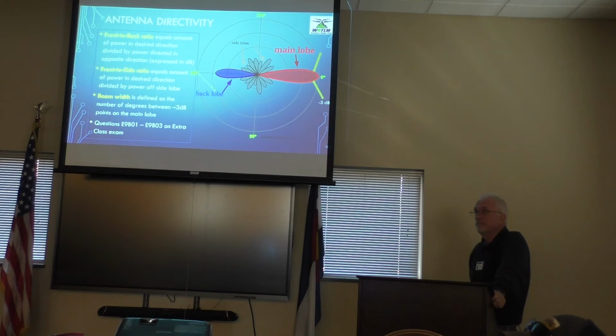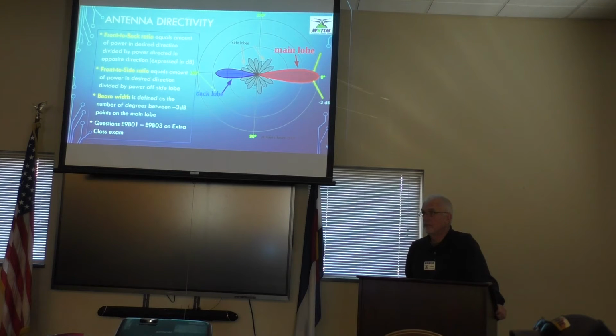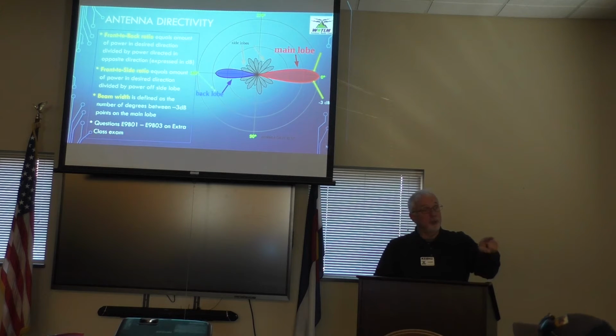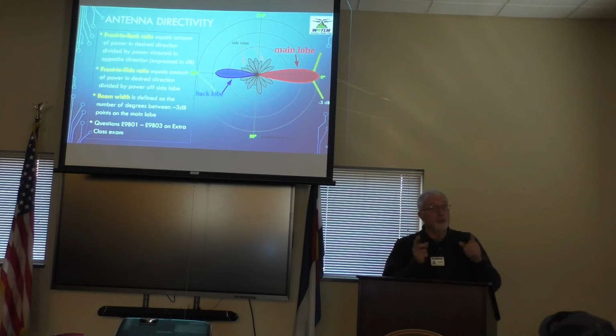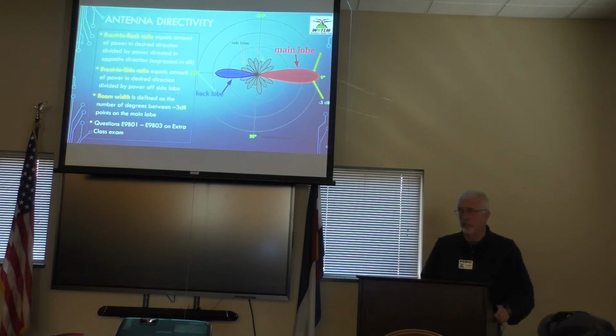Mitchell? One of the things that's really interesting about those older television antennas, if you look at them, almost all of the elements are actually connected to the driveline. So it's not a Yagi type antenna, they're not acting as reflectors. They're different tuned elements for the different channels because they're fairly widely different frequencies. So you can really think of it as just a bunch of stacked antennas. Yes. So to your point earlier, you could probably not change the performance of it by taking elements out. But you need to make sure what frequency those elements were really for, and that's what makes the log periodics really broadbanded.